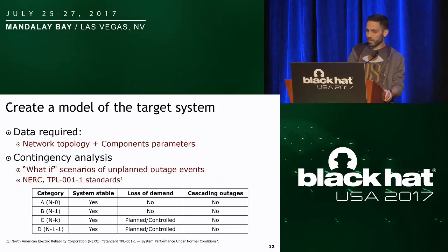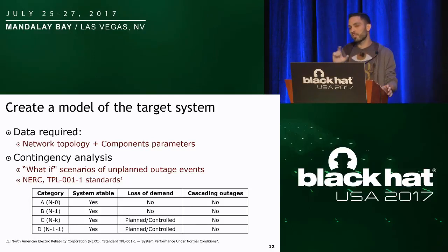A particular type of study is named contingency analysis, and it's a major activity in power system planning and operation. In layman's terms, contingency analysis is a what-if scenario simulator that evaluates the effects and calculates any overloads on an electric power grid when a problem occurs. A contingency, for example, can be the loss or the failure of a small part of the grid, such as a transmission line, or even an individual component, such as a transformer or a generator.